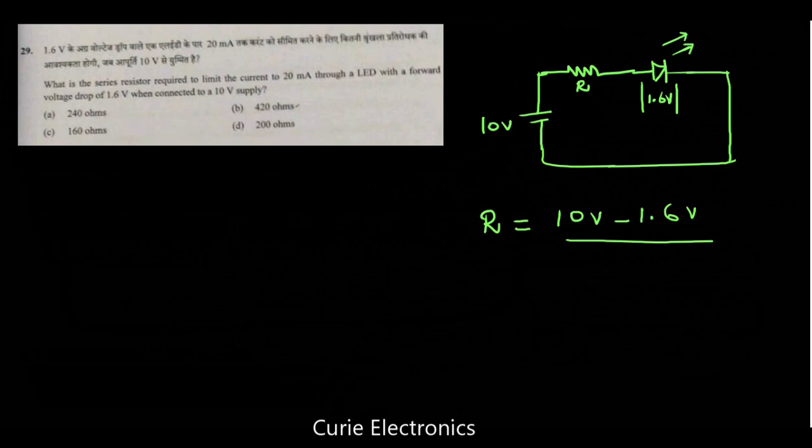The LED requires 20 milliamps. 10 volt minus 1.6 volt, we will get 8.4 volt upon 20.